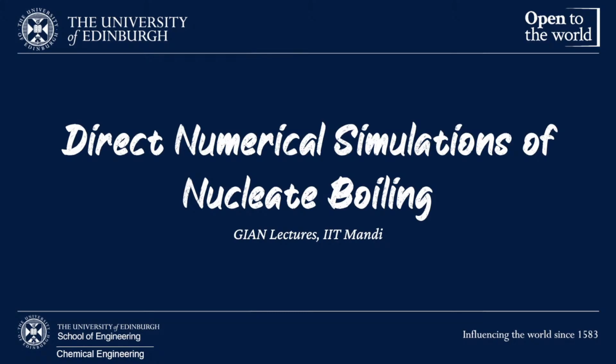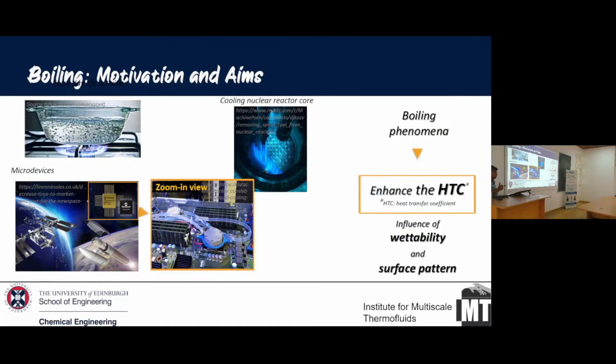In case of boiling, it's a very fast phenomenon. All it has to do is take in heat from somewhere, change its phase, and conduct the heat the other way. An important aspect is that boiling is very important, whether it's nuclear reactors or microfluidics; we even use boiling for cooling microelectronics. But the most important thing is that boiling is dependent on wettability and surface pattern, and this is what we're going to see now. Here you will see the Cahn-Hilliard model in its full force.